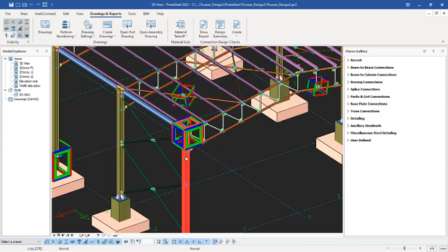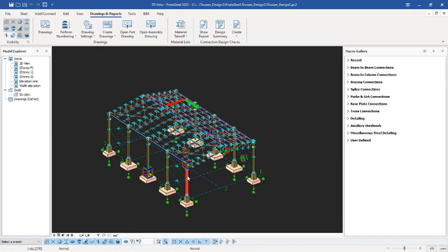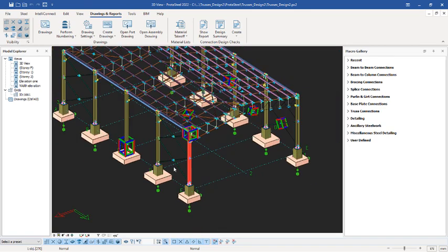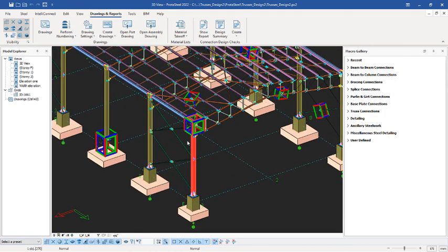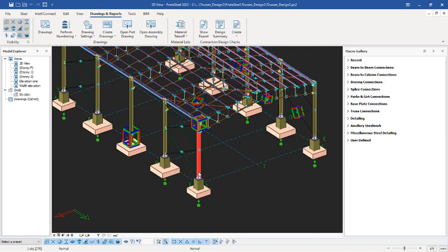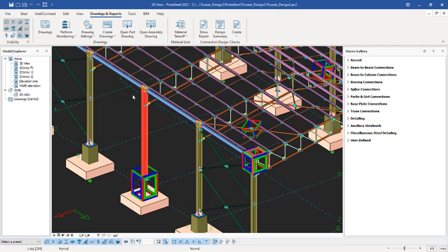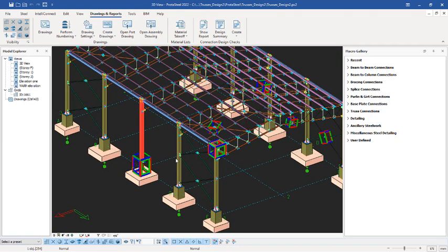Okay, I can just pick these members now and create an assembly drawing for this member, and I know that this type of member, I have it 1, 2, 3, 4. So any drawing result I have, I multiply by 4 to get the drawings for this particular member that is at the external edge of this structure. So I can pick this one for the internal. So this one now can serve for this and this. Okay, so we have 3 this side and 3 the other side. Altogether is 6. So if I get the drawings of this now, I can multiply it by 6 to get the actual number and the detailed drawings of the intermediate stanchion successfully.